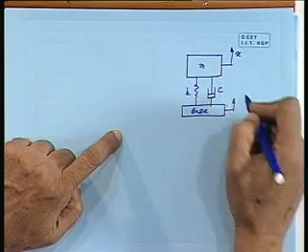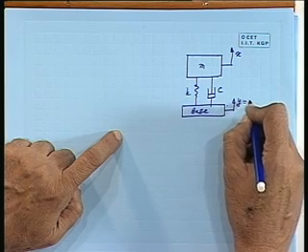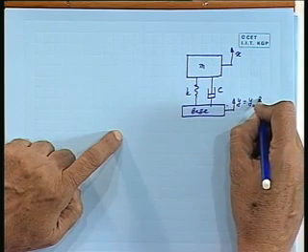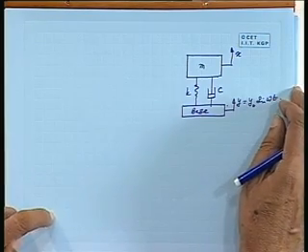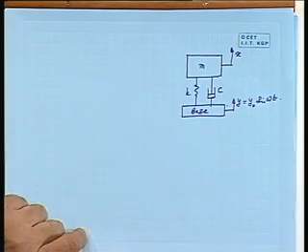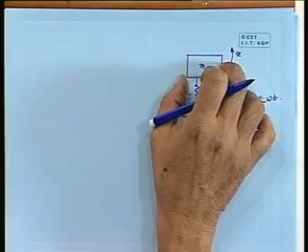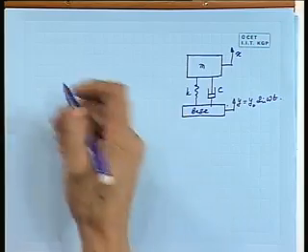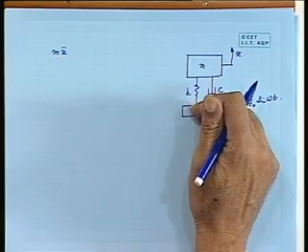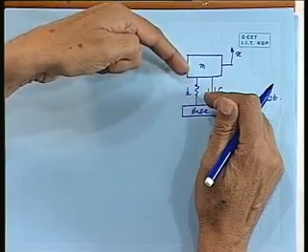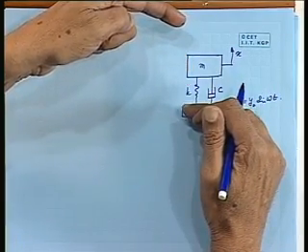So, equipment displacement is given by x, foundation displacement is y, which is given by y0 sin omega t. Okay. Now, if you draw the free body diagram of this, what happens? The inertia force is m x double dot. What is the force coming here? x dot is this velocity and y dot is this velocity.